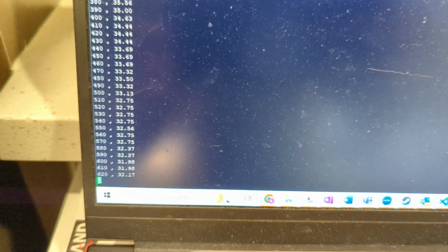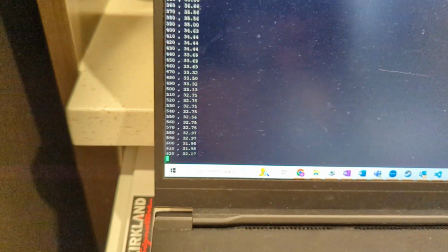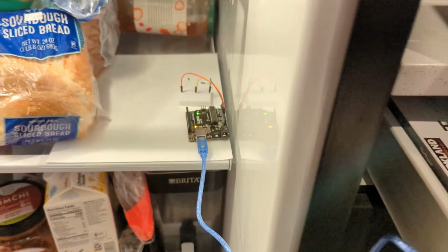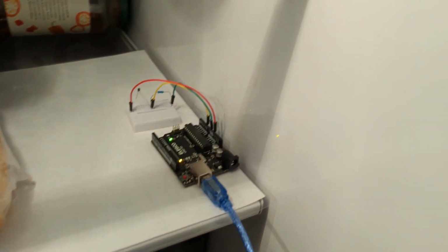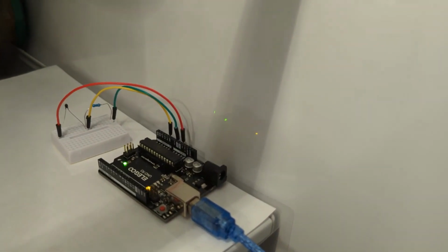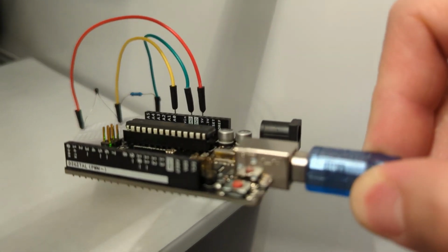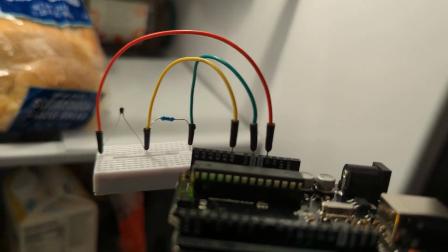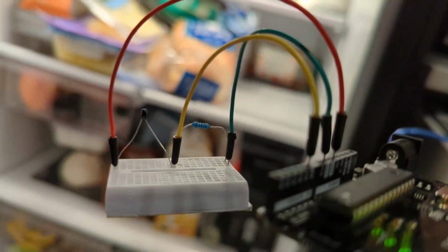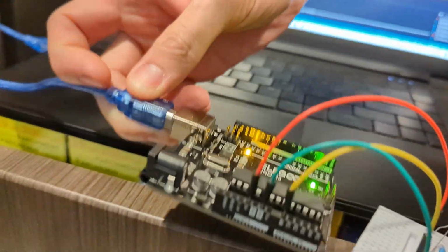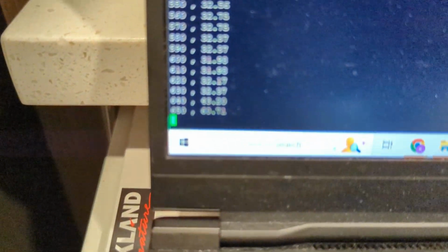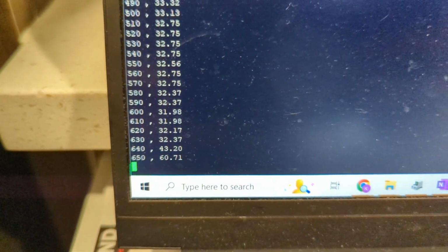Might be the reason a lot of my produce is getting icy. So that's a knowledge point for me. Also just accuracy of the temperature sensor itself, which might not be perfect. I can certainly calibrate the system a little bit, knowing the resistance value of the reference resistor in my voltage divider circuit. But I'll go ahead and clock this at 650 seconds.